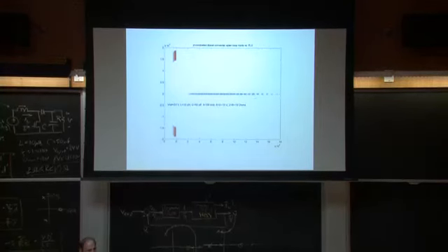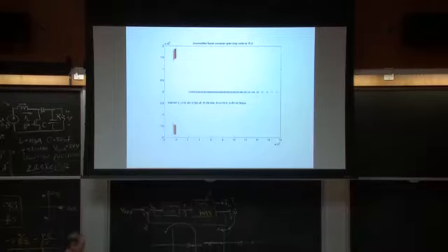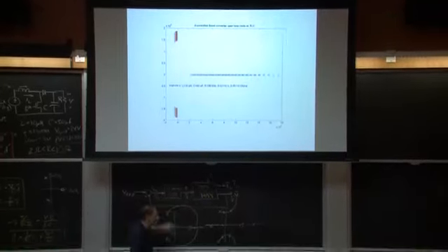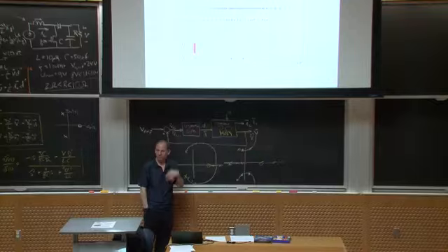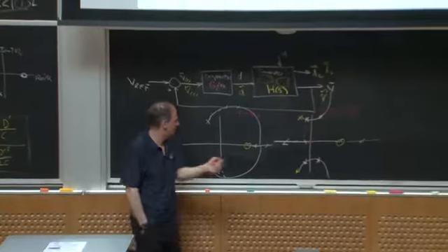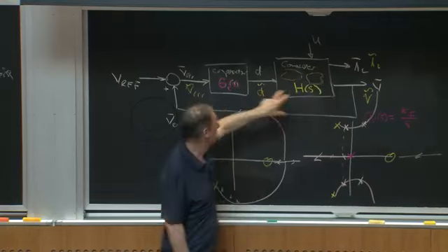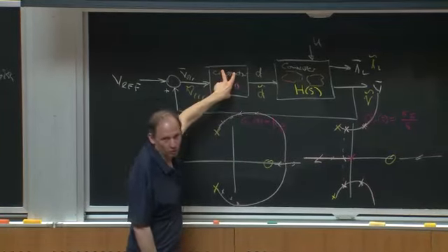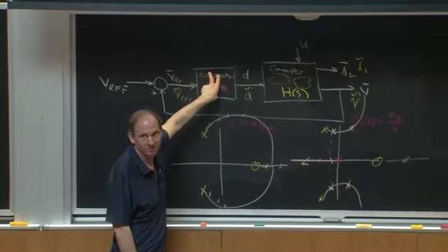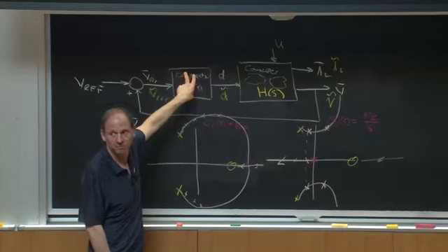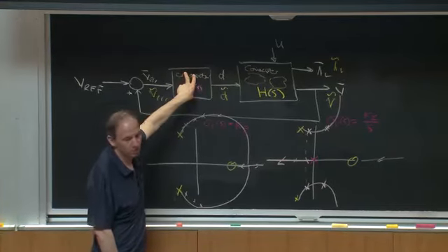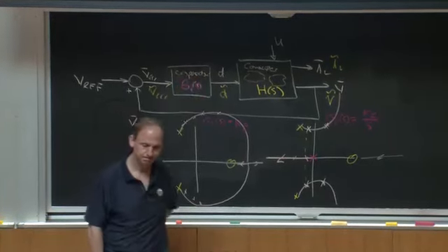So any compensator I'm going to have to build. The typical thing you do, you could build a variable compensator that did different things for different operating points, but the most typical thing to do in a DC-DC converter is to say, I know my plant characteristics vary, let me design one compensator that'll work for any location on that. That's the simplest thing you can do. Okay? And so let's see what would happen if we try to do that.